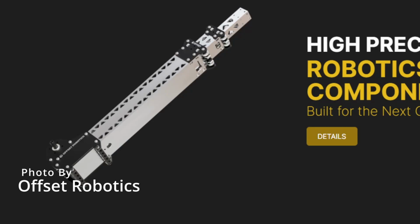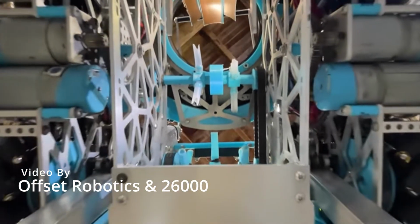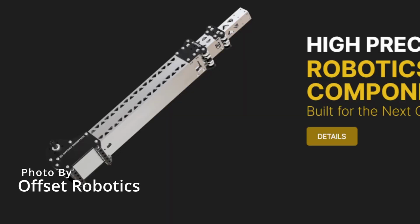Box tubes are another way to achieve this motion, incorporating nested tubes that use string and pulleys to extend. I first learned about this type of slide through KookieBots in Center Stage, but since then they've been popularized with Offset Robotics selling their very own, and Theseus recently using them to earn their base points. This mechanism differs from the usual slide extension, as they are rigid squares instead of thin drawer slides. This means only one set of box tubes is needed to eliminate backlash when there would usually be 2 sets of drawer slides to achieve the same effect.